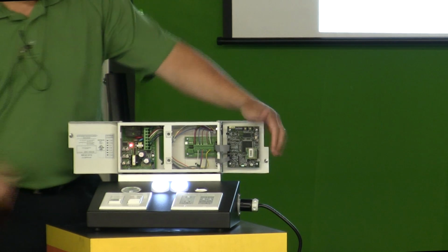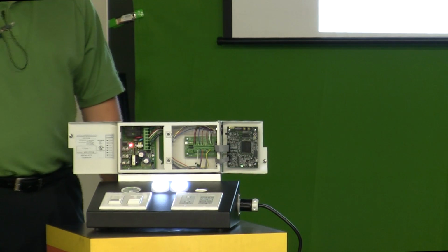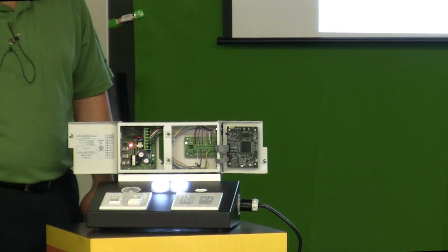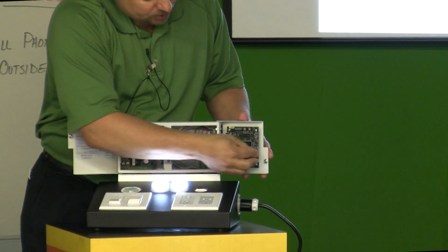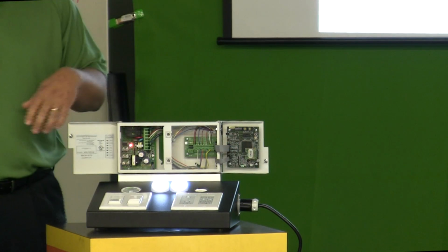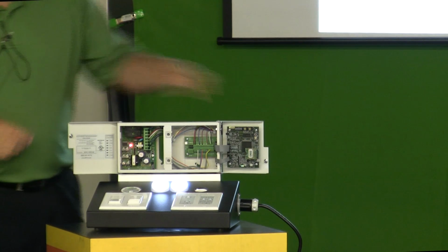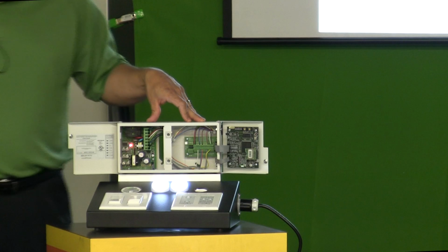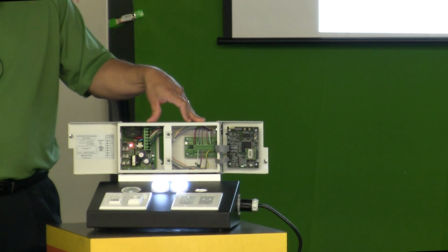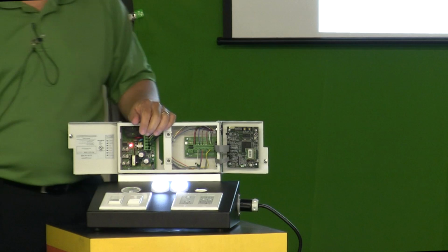This happens to be what we call an optional Bluetooth radio. So if you didn't order it with the Bluetooth on it, you could add that at a later date. What that does is basically allow your technician to program the system from the ground. It also allows you, once you've made this connection to this module, anything else on the MSTP bus that's one of our devices could be seen through that port, so it's tunneling basically through there.